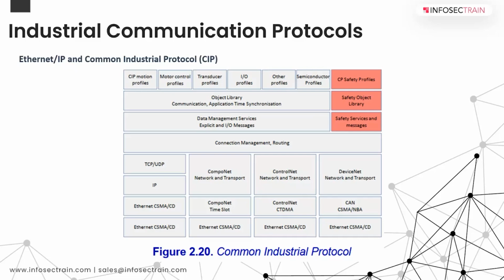Right. So we were talking about the CIP protocol. Ethernet IP defines two connection methods using TCP/IP: explicit messages using TCP and implicit messages using UDP. Ethernet IP actually is much more commonly used, as far as I've seen, in some of the industry sectors. So it is again good to know the implementation of the Ethernet IP protocol.